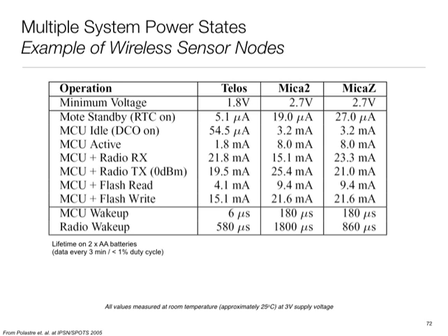So I have picked some old examples because in early days of the field, people would characterize these things a lot. And you would see that there's a fair bit of diversity, but there are certain numbers which are very important for us. Firstly, certainly how much active power matters a lot, but in many applications, I'm mostly asleep. And this goes back to the issue of doing nothing well. And when it comes to doing nothing well, in this case putting things to sleep and waking up, there are two numbers which become important: how much we are consuming when we are in idle or standby mode, and the other thing, the wake up number.